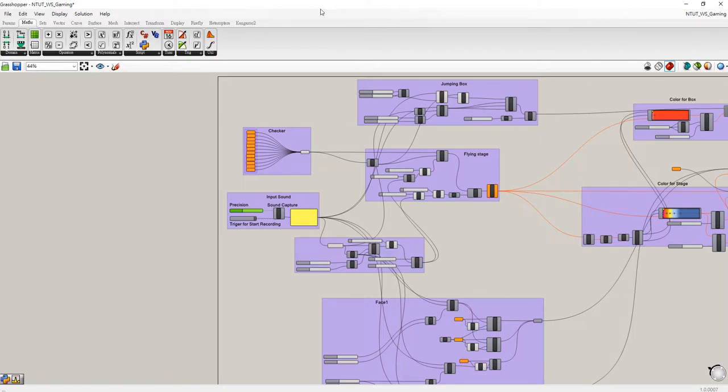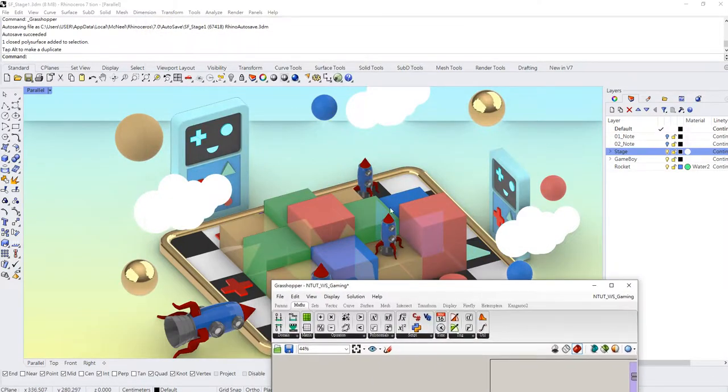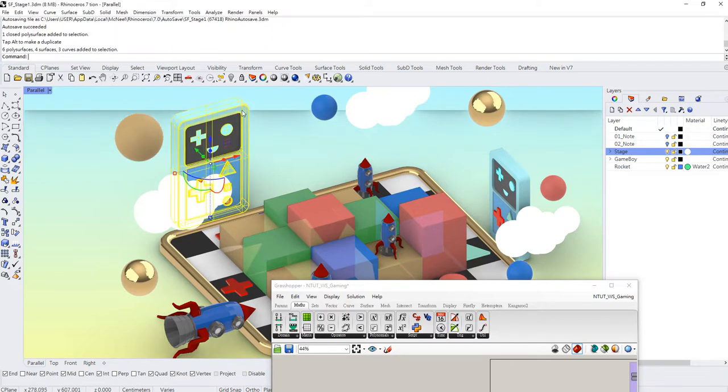So a very important thing is that when you are going to design your model, try to make it simple. Some people like to use a subdivision model, but a subdivision model has a problem because it actually contains a lot of faces. So that's why I ask you, if you want to make them move, it's better to use an instance surface. It will be easier and also faster. And if you're using a mesh model, make sure you keep the polyfaces lower, just like this.